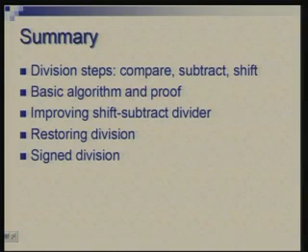Then we brought in the concept of restoring division. Initially you carry out anticipatory subtraction. There is no comparison involved here now. Subtraction is done unconditionally, or I should say blindly you subtract and then restore. Then we saw that restoration can be postponed, which simplifies each iteration, and of course, it made it necessary for us to have a final step where a final restoration or final correction was necessary.